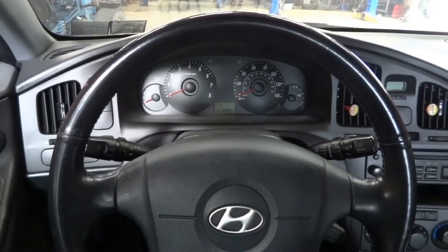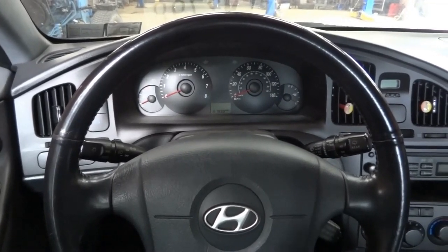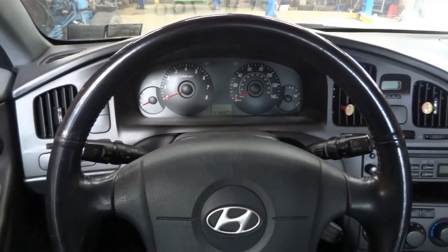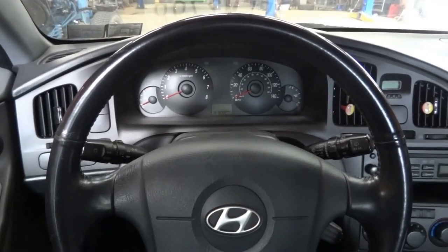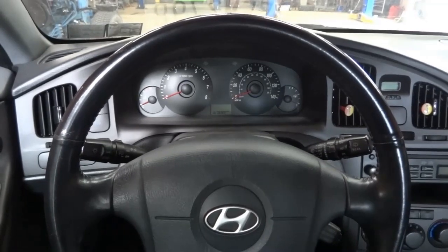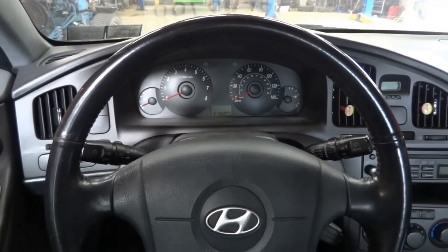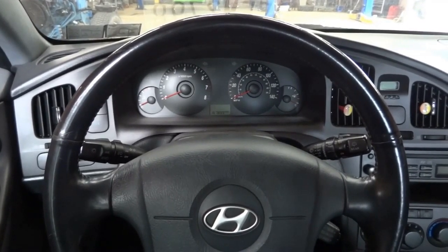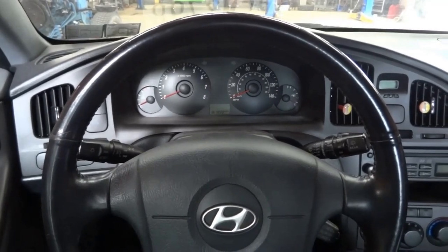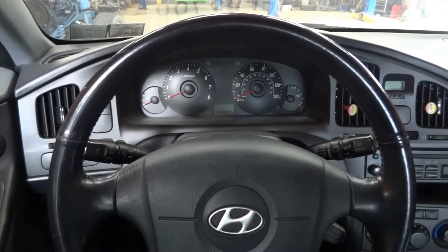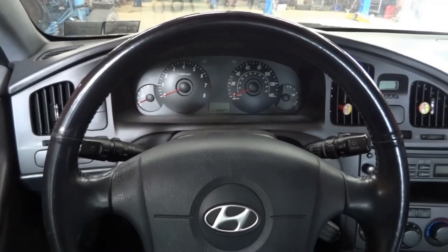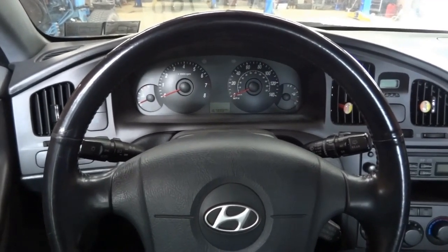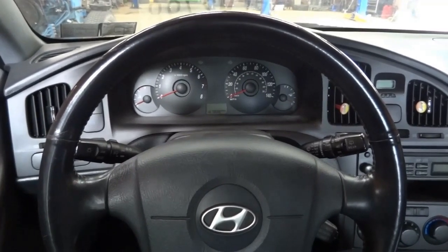We also analyzed the data after the repair to look at our fuel trim numbers to make sure that the engine is not running rich or lean, because if you have a rich running engine, it's going to damage your catalytic converters again. You can replace 10 catalytic converters. If you don't fix the cause, the concern will be back. So that's why I test drove this vehicle with the scan tool connected to the car to see if this engine is running good. And the engine is running good.